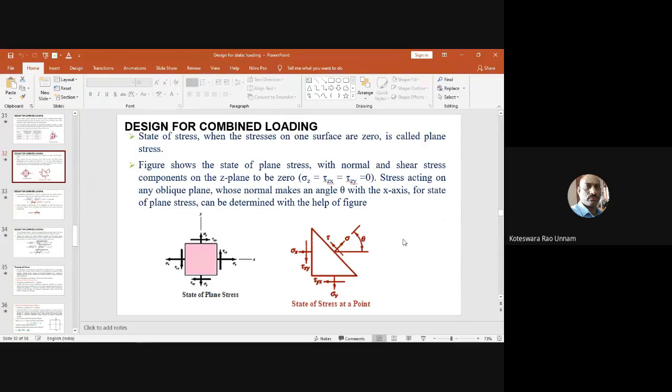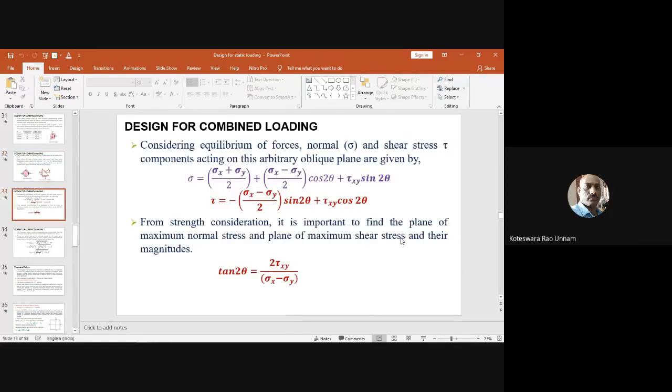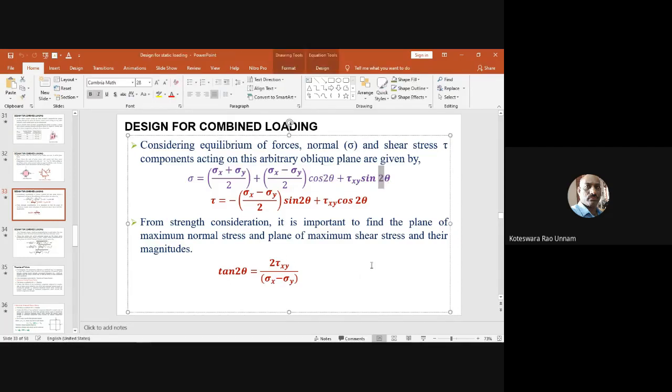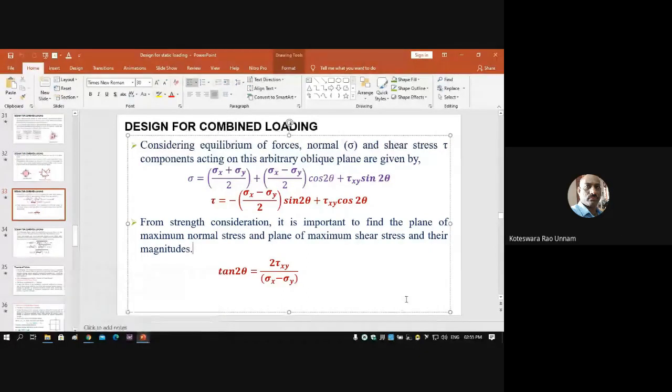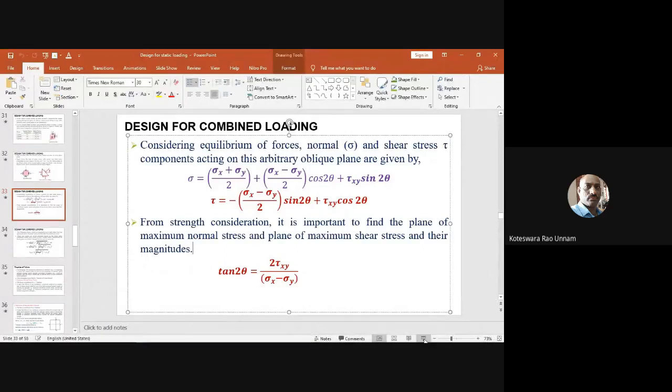Why is it 90 degrees? Mohr circle, sir. In the Mohr circle, what do you do? Each angle you have to represent by 2 theta, right? Sigma 1, sigma 2, we assumed they are perpendicular to each other. Sigma 1, sigma 2 are perpendicular? It is a biaxial state of stress, sigma 1, sigma 2.